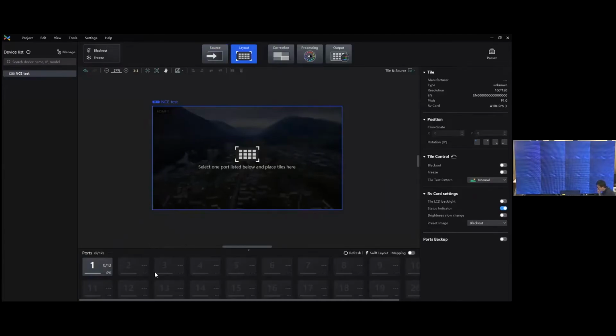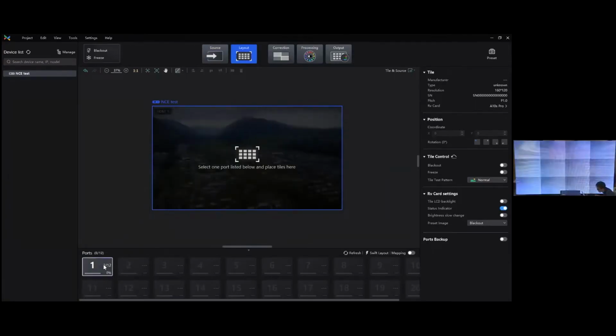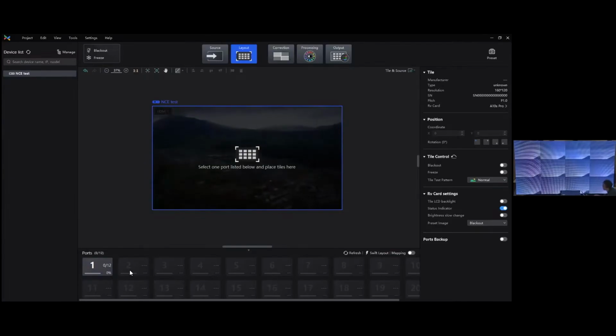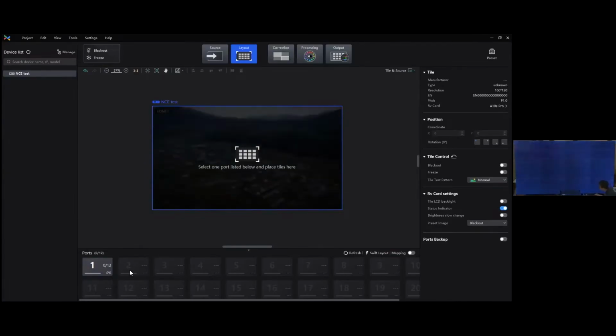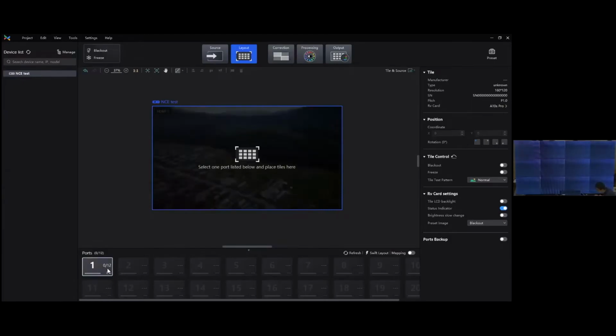You can see from the canvas at the bottom of the layout, here just has one port. You can select it or deselect it, and the other port is gray, which you cannot select. That is, in the VMP software, it reads the data information from controllers in real time and directly shows the result for you. So you don't need to count which port is loading which part of the LED screen, because VMP already tells you directly here.